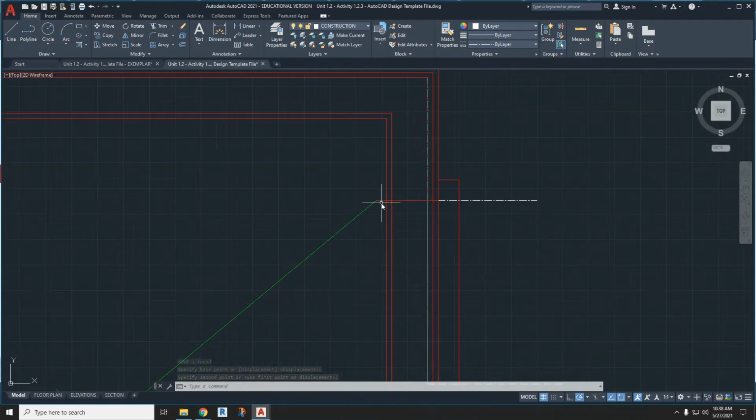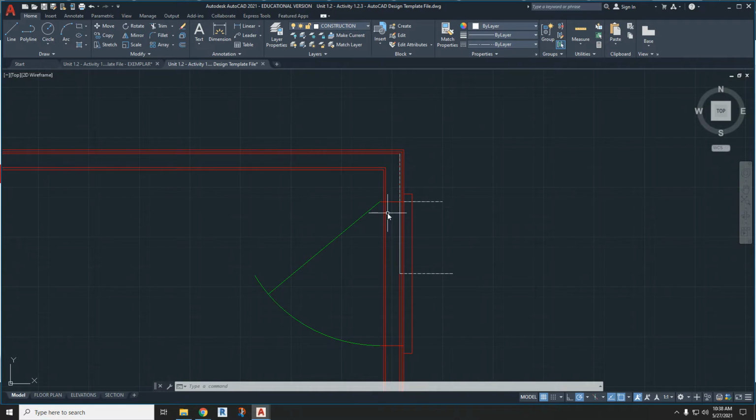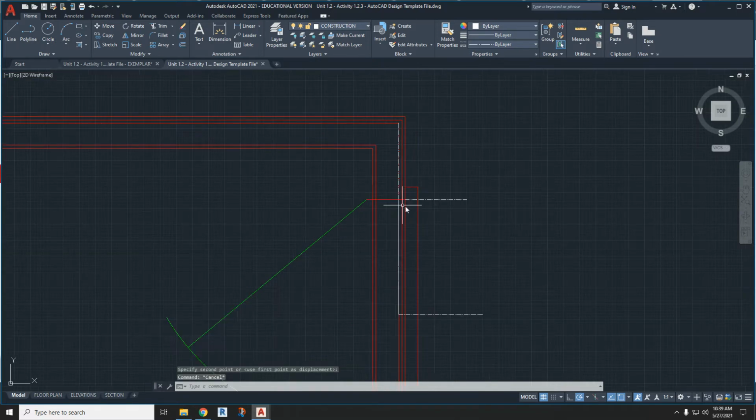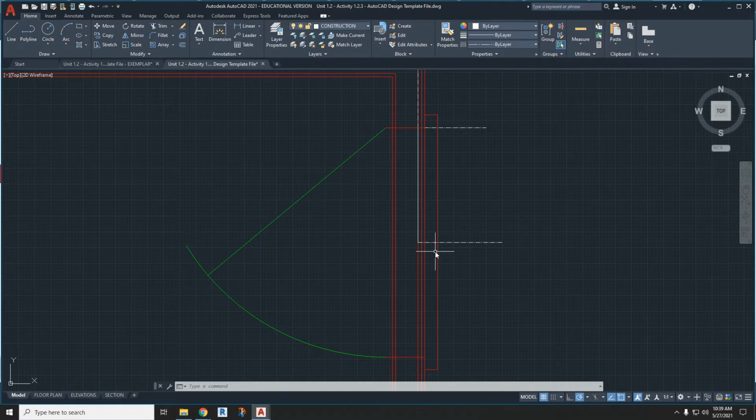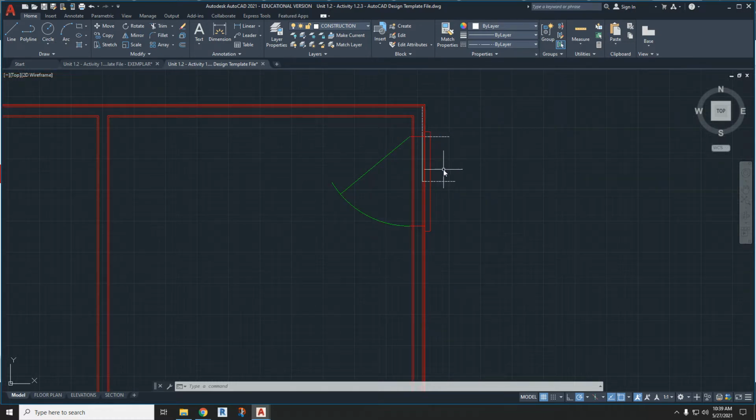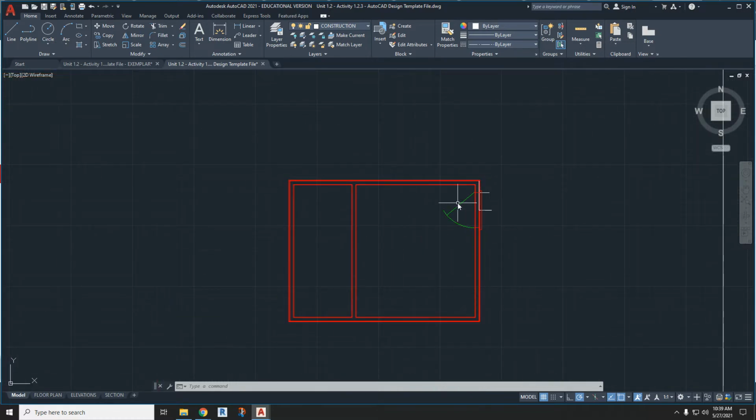This isn't perfectly sized. I think this is set up to be for a 2x6 wall instead of a 2x4 wall. This is not that level of detail. We're going to make that kind of correction right now. But when you dimension doors and windows, any rough opening, you dimension to the center of it. So that's why I'm going to leave this mark, and this just helps me place it because I place by that. All right. So that's that door.